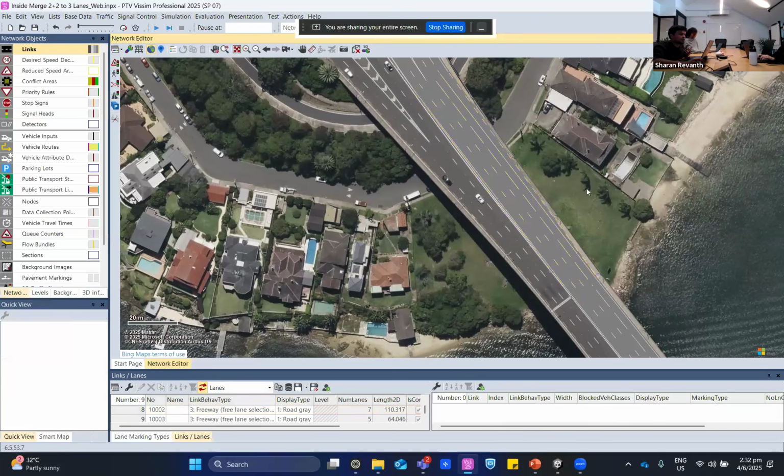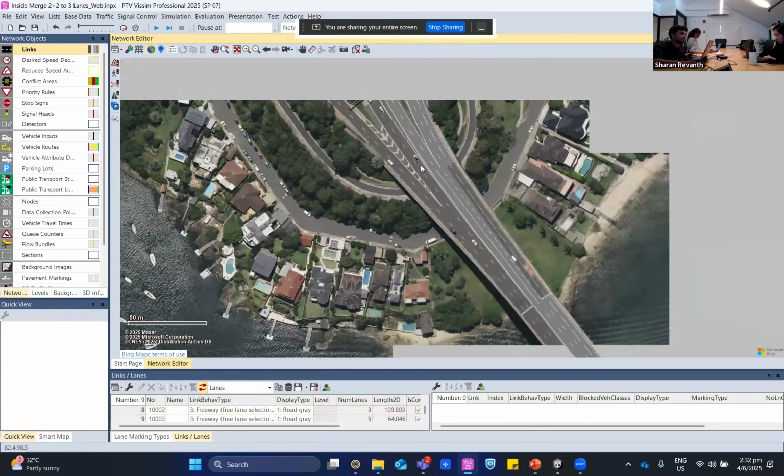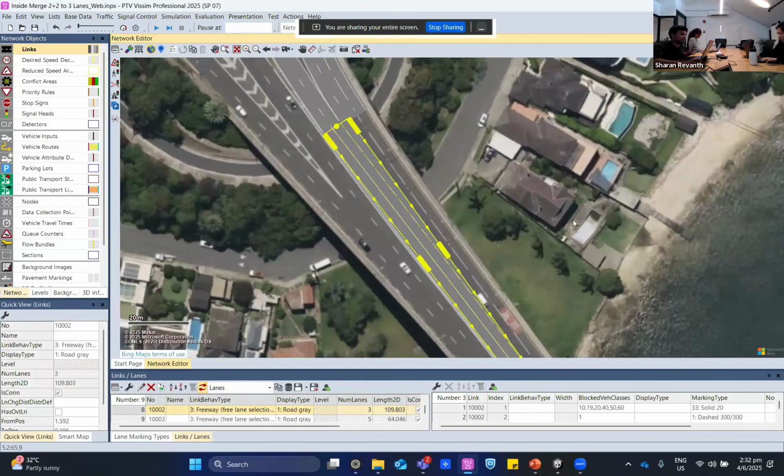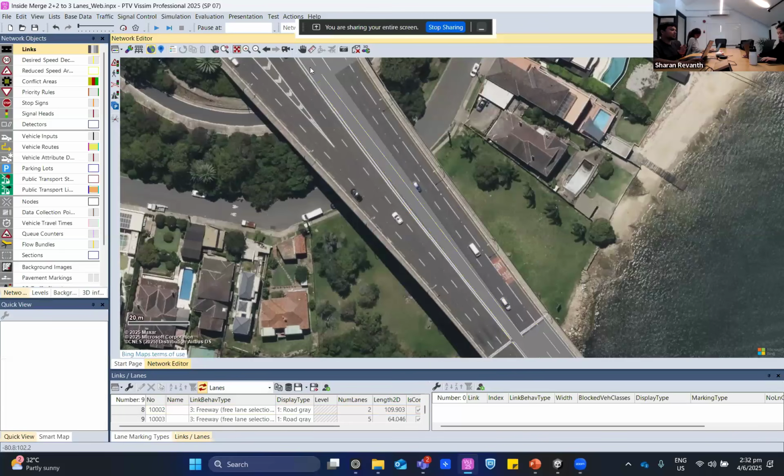First, you will always get these rectangular boxes, which indicate you can adjust at these points. So first let me reduce it, and let me focus on the first 2 lanes. I'll move these yellow dots to here. Let me finish the first 2 lanes, and then I'll move on to the other lanes. Now I have converted a 2-lane merging into a single lane here.